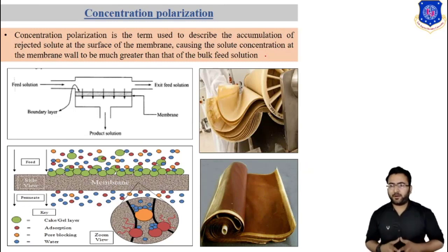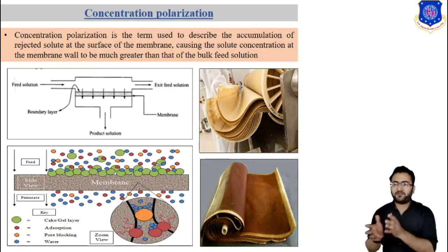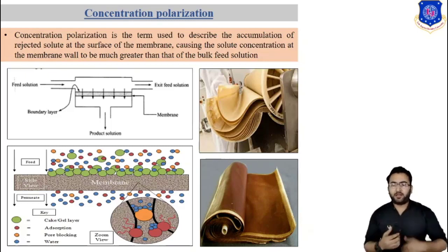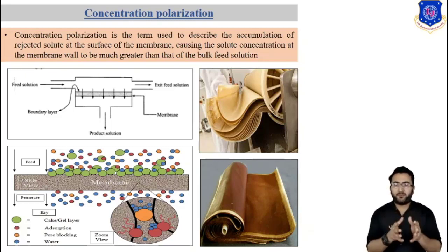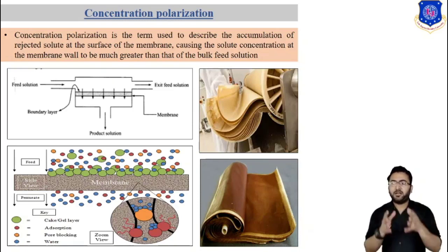Now let's discuss concentration polarization. Concentration polarization is a term used to describe the accumulation of rejected solute at the surface of the membrane. The solute concentration at the membrane wall is much greater than that in the bulk feed solution, as shown in this figure.